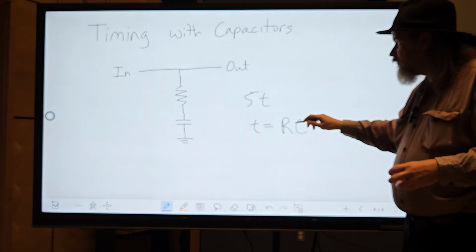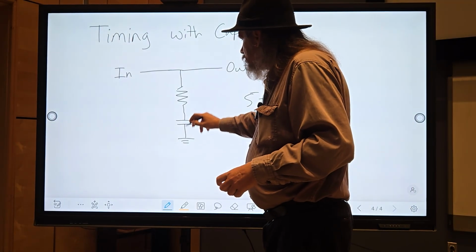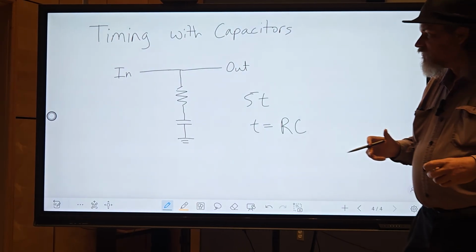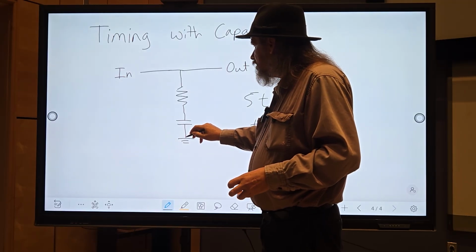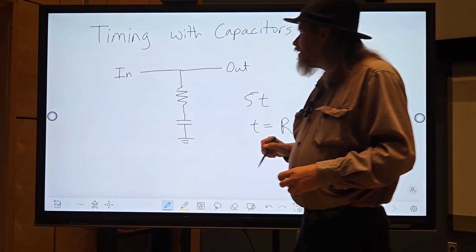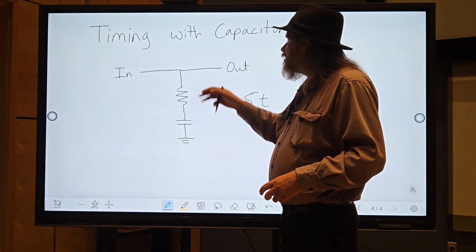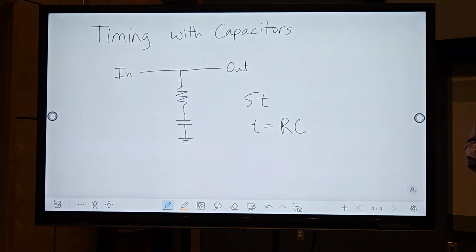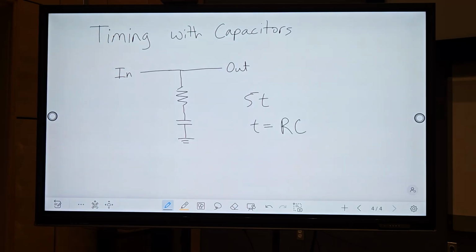But this will hold a charge for that period of time. This is how you can store a value, 1 bit, in a capacitor. Either the charge is low or the charge is high. But you go ahead and charge it to store the bit in memory, and then you turn off the input, turn on the output, and you read the bit from memory. I think that's about it for capacitors.